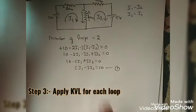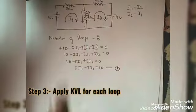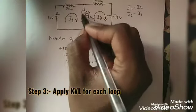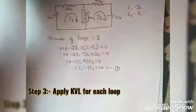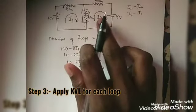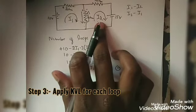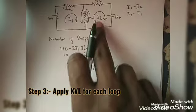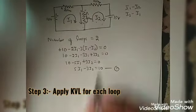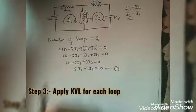Now we'll apply KVL for the second loop. While applying KVL for the second loop, we'll take the direction as plus minus, and since we are applying it for loop 2, we have assigned the current as I2. When we consider this loop, I2 is greater than I1, so we'll take the net current as I2 minus I1.